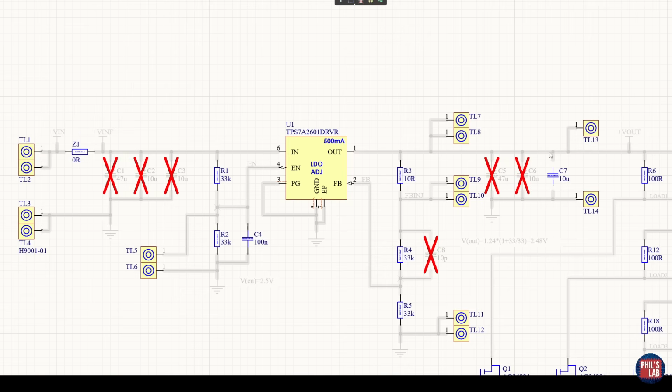What we'll measure with the Bode 100 is the ratio of the AC output signal, or ripple, relative to the AC input signal, or ripple. Then that ratio of those two, output AC to input AC, gives us the power supply rejection ratio. And of course we want a lower number for the power supply rejection ratio because ideally we don't want any output AC ripple, given any input AC signal at any frequency, any amplitude. But of course that isn't possible, as we'll see.